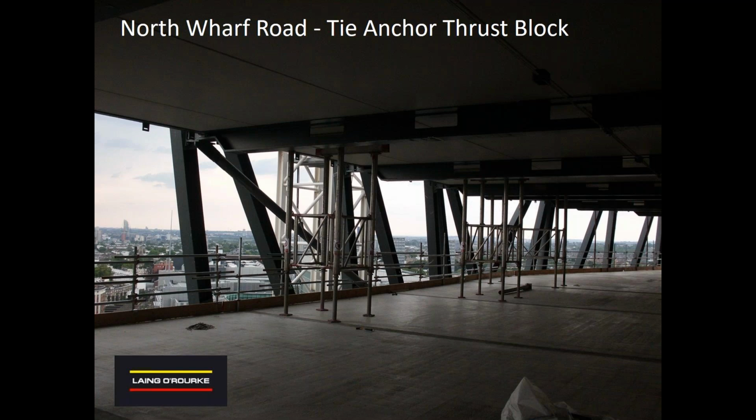But the idea is that the tie is attached preferably around midspan of a temporary steel bridging column, a hollow section, which then would be bolted to the slab above and bolted to the slab below. The obvious advantage compared to a thrust block is you're transferring the loads from the tie into 2 slabs as opposed to 1.